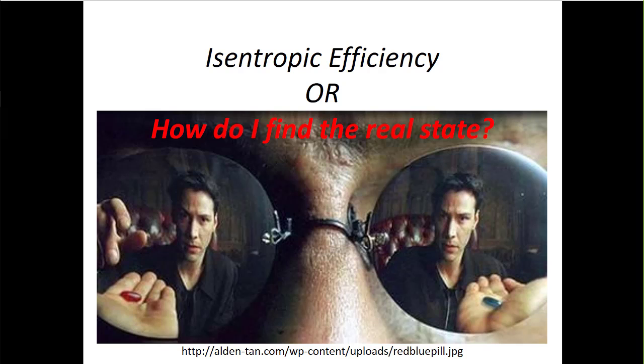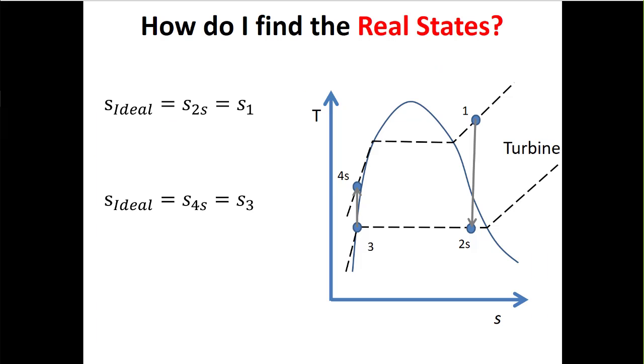Compressors are essentially the same thing as pumps, but we talk about pumps when we're talking about moving liquid or increasing the pressure of a liquid. And we talk about a compressor when we're talking about increasing the pressure of a gas. So we talked about this curve here, right? So the ideal turbine and the ideal pump are vertical lines, right? The turbine goes down from high pressure to low pressure. The pump goes up from low pressure to high pressure.